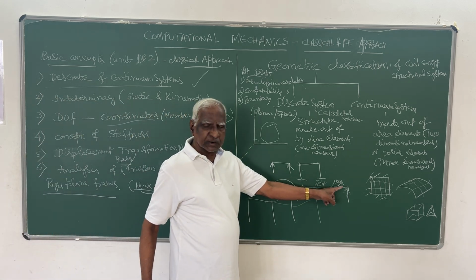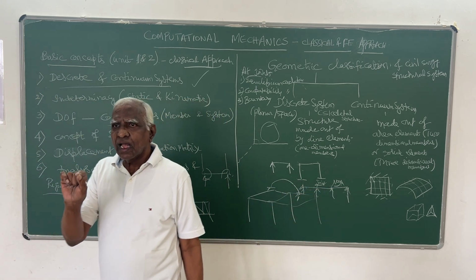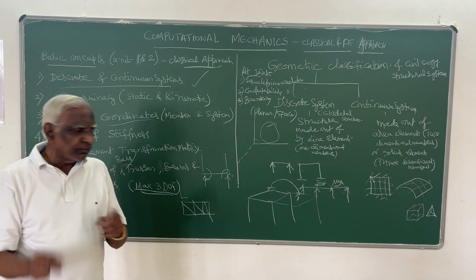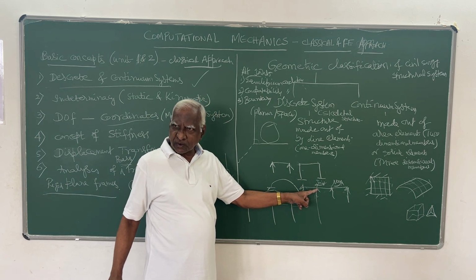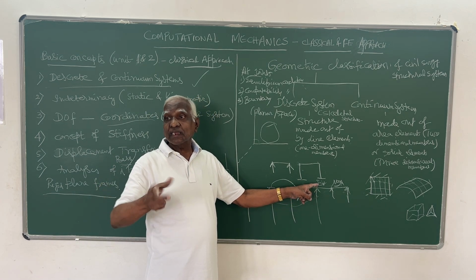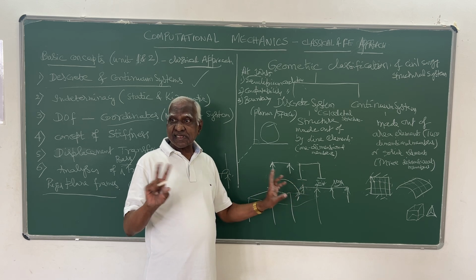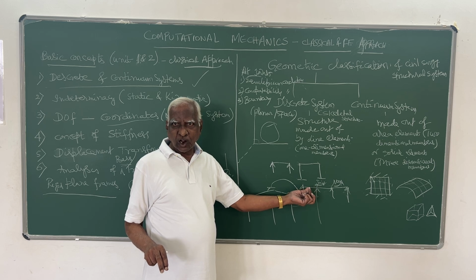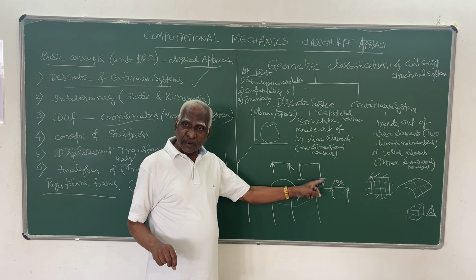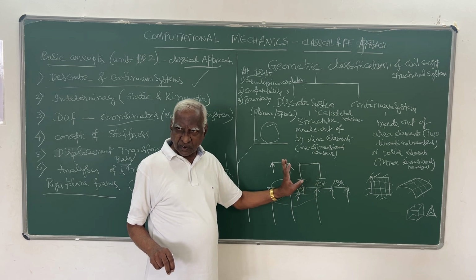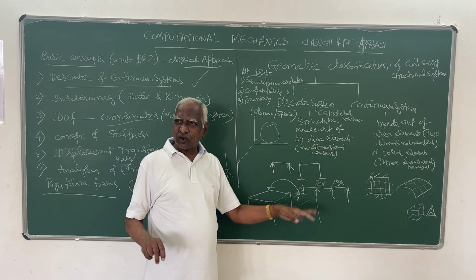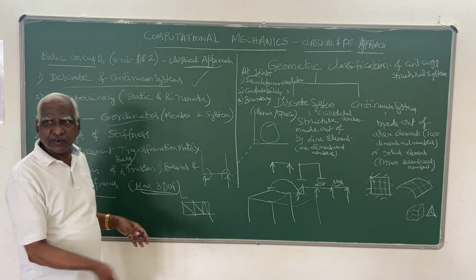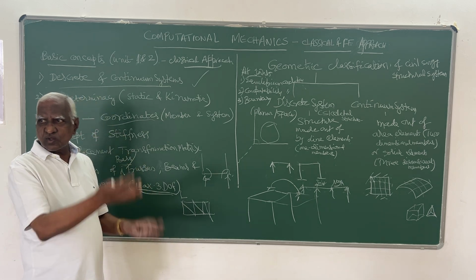Again, these nodes or joints, either it may be pin variety or it may be rigid type. Right? Pin type of node is that particular point wherein the rotation is allowed, but translations are not allowed. Right? There will not be any translation. Rotation is allowed, pin joint. So rotation is allowed, means no moment, because no restriction, no moment developed. The rotation is free to occur. So there is no resistance, there is no moment.